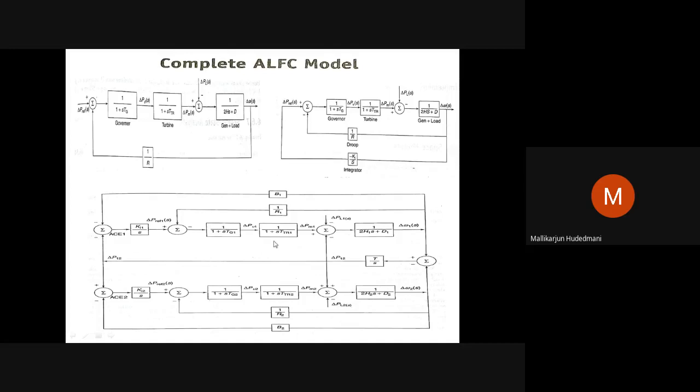Earlier, only the primary control was seen. With supplementary control, when the integral controller was seen, the stability of the frequency deviation and the error coming down to 0 was visualized when the integral controller is utilized. That concept is utilized here. Now, how can this be re-understood? What is the meaning of ACE1, ACE2? How are these values computed? So we can think a little further here.